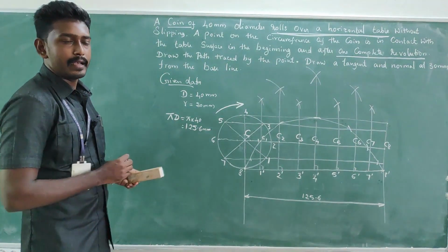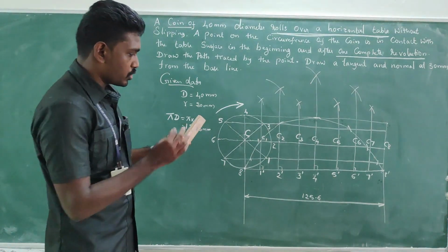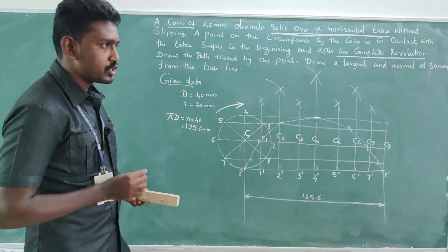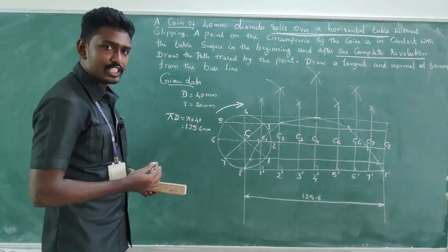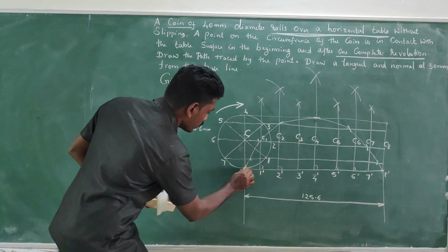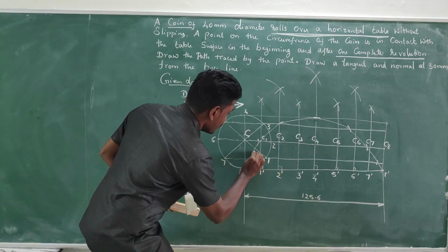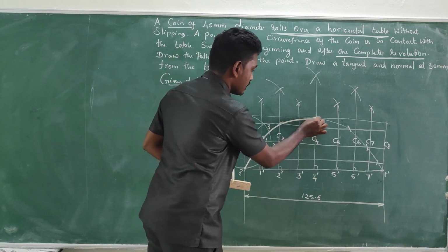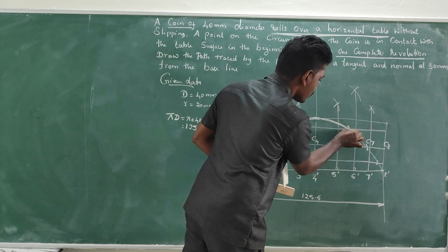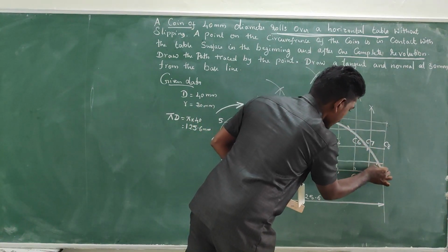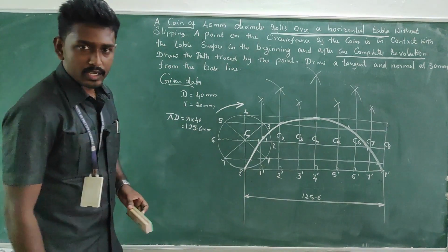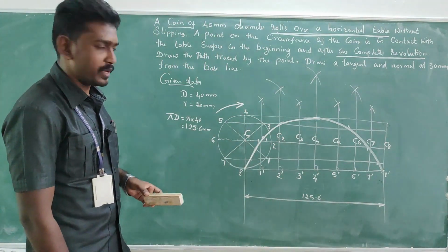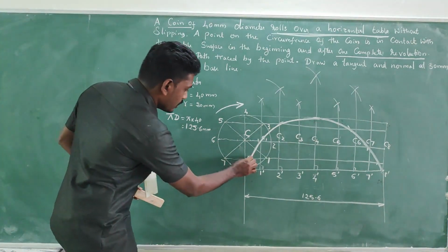Once you are strongly convinced this is the exact cycloidal shape, you can take the 2H pencil or HB pencil. You can take the HB pencil and go for a very dark line, because this is the exact required part. You are asked to draw this curve, right? So this is the cycloid curve. So we have to make it as dark as possible with the HB pencil. Okay, and next we can give the point numbers.